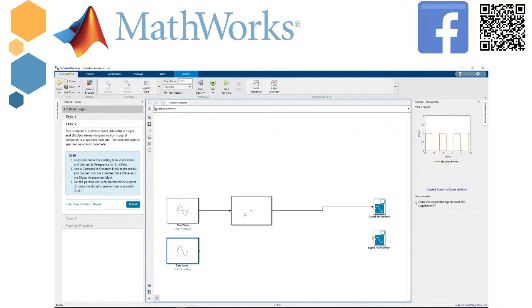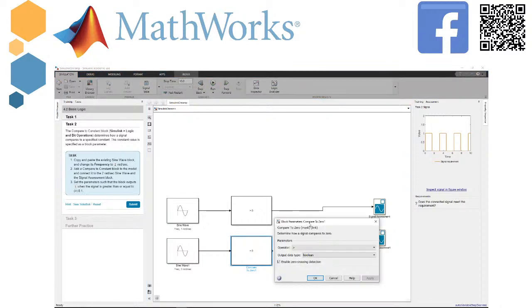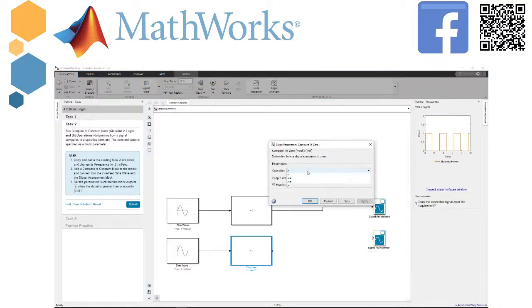We will see that if the velocity of the car is more than 100 km per hour, or it's more than 35 km per hour but the lateral acceleration of our system is greater than a value, we need to insert a certain mode on the car, so the car can understand what is going on during the driving.